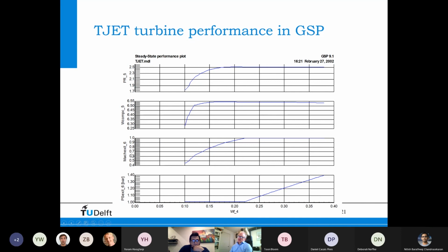And this is the Mach number at the exit of the throat, and this is 1 here. So you can see that in the low power region of the turbojet engine, the nozzle is not choked, and that's because all the pressures and levels in the engine are much lower. And here you can see that the pressure ratio of the turbine is also staying the same.